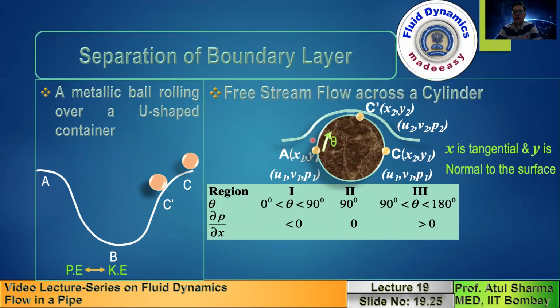So if you consider yourself as a fluid particle, you are moving upward, and what you are finding is the pressure ahead of you. Let's suppose this is a fluid particle, it is moving. The pressure ahead is less. The pressure behind is more. So you have a net pressure force which will push you along the flow direction that leads to the increase in the velocity.